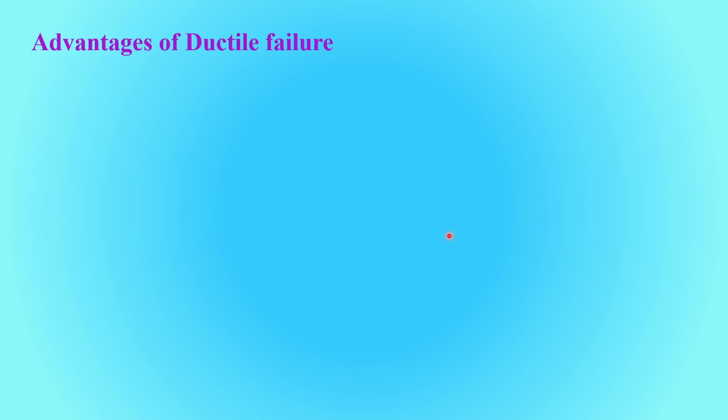Now what are the advantages of ductile failure that we want? Advantage of ductile failure: it avoids breakage even at large displacement. So during an earthquake there will certainly be displacements, and depending on the force exerted from the earthquake, there may be large or small displacement. So if your system can survive the large displacement, it will survive collapse.